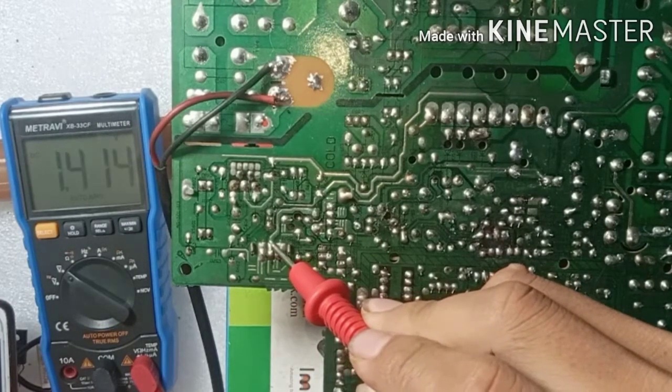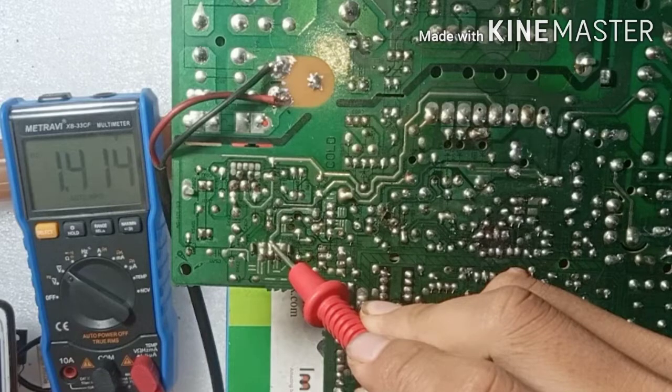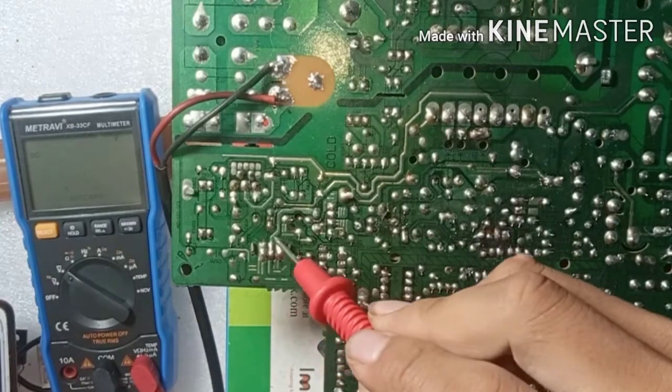Here it goes. Oops, we don't have enough input voltage, just around 1 volt. This cannot happen because 1 volt cannot be regulated to 5 volts. There is no such thing as free energy. Maybe there is a broken line within this section. So I'll follow the path. Here we go.